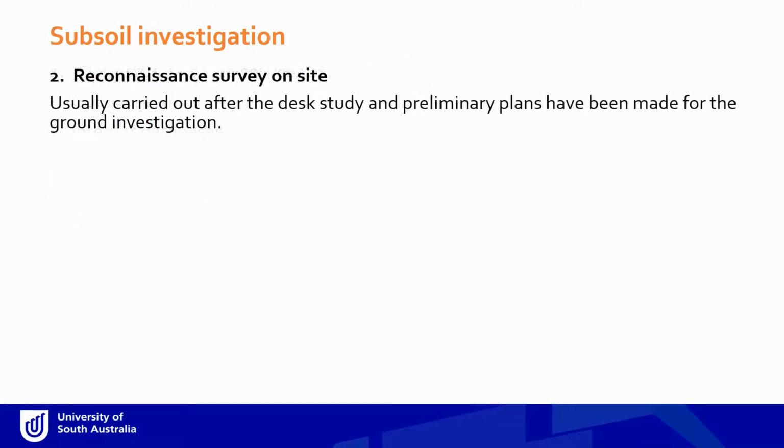They can be a valuable source of information as well. Now, once the desk study is done, the engineer or the geotechnical or subsoil investigator will go to the field and do a walk-around survey and do some of the visual tactile tests we learned about when we were studying soil classification a couple of videos ago.